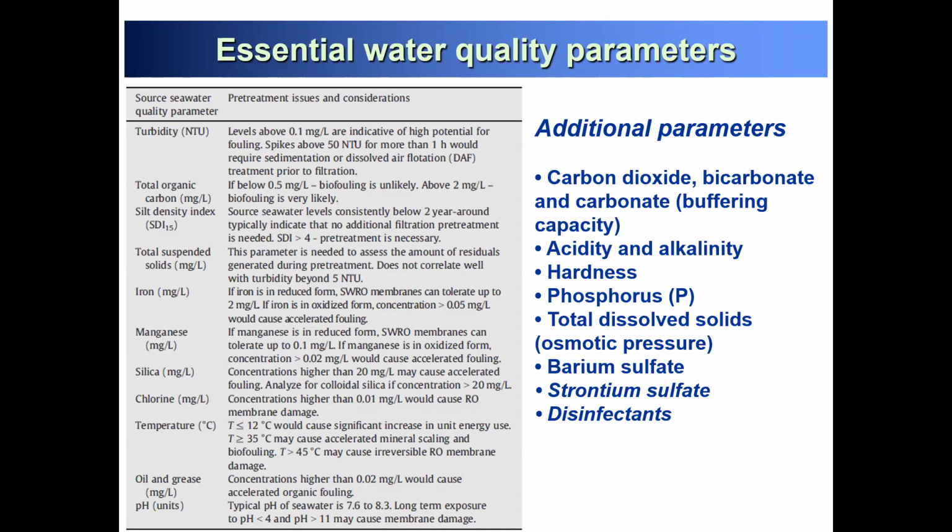So you have a dissolved salt. Dissolved salt creates your osmotic pressure because of the concentration gradient across the membrane. So you have seawater here with 28 bar of osmotic pressure. You have a membrane here, and then you have to apply pressure more than 28 bar. Otherwise, you cannot control your water molecules in this membrane.